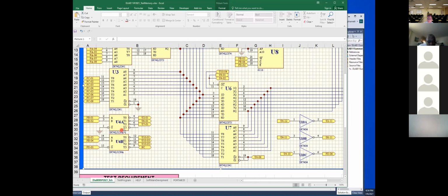And again, the pins on U4 that control both U2 and U6 both run through inverters. They control U2, U6, U7. So when you have U4 pin 11, when that comes high, it comes out low for U6 pin 11. They run through inverters, so you get the opposite effect. That's the logic. That does not affect anything here.